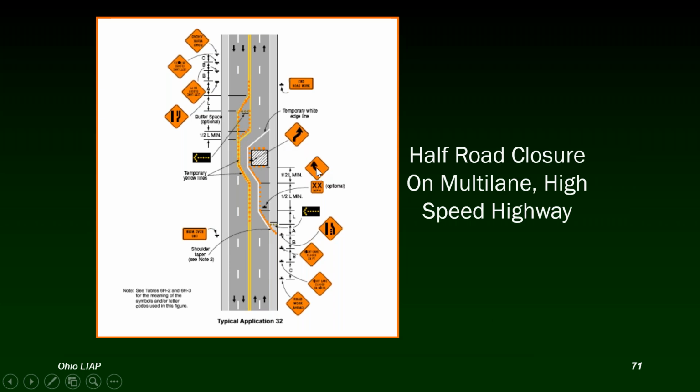So you see the shifting to the left arrow and shifting to the right arrow for the before and after the actual workspace. And in the southbound traffic, that's the southbound right lane. So that's a typical right lane closure for southbound traffic. So the right lane closed ahead, etc., to get them over into the southbound right lane. As you'll notice, there's a buffer space for each direction.